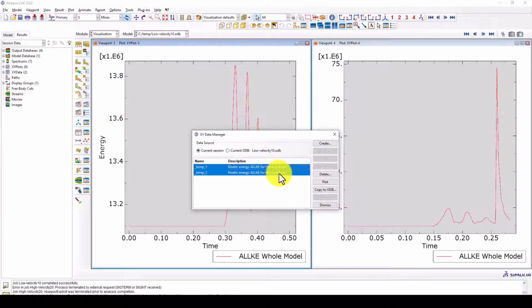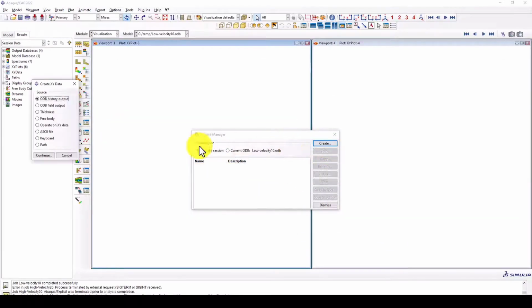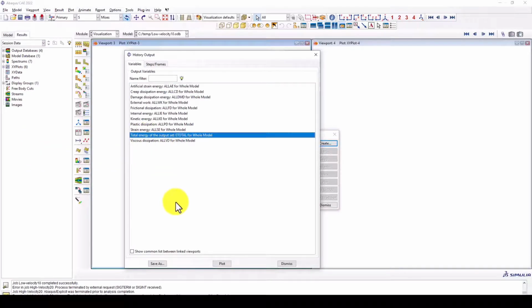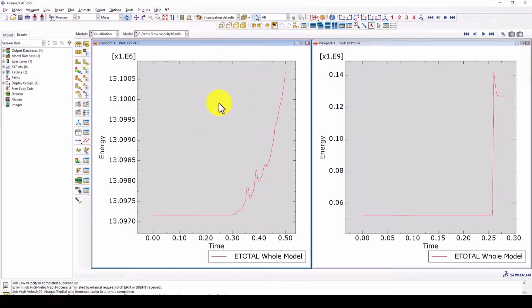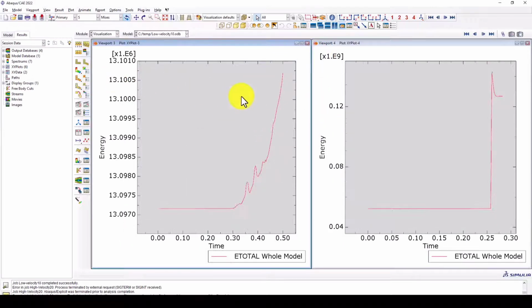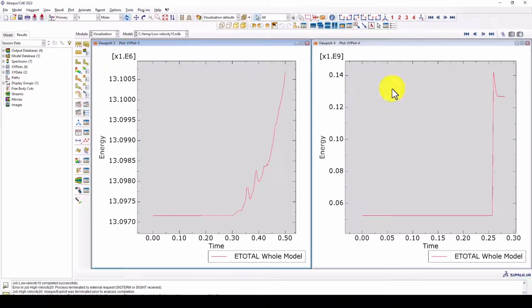For example, imagine a ball hitting a plate at an angle. Now the contact forces have both normal and tangential components. Now just note down that friction can influence ball rotation, sliding, energy dissipation, rebound direction, and local stresses, as I told you. Therefore, contact properties should be set up based on experimental data whenever possible and not on your intuition.